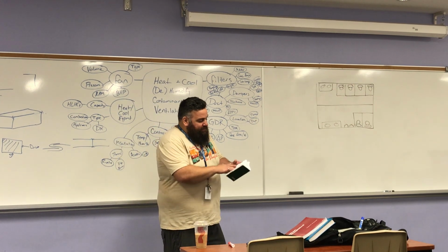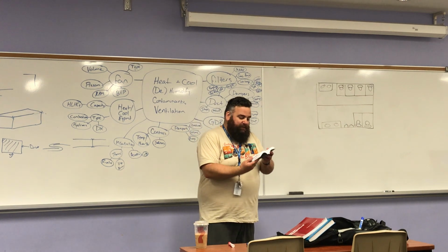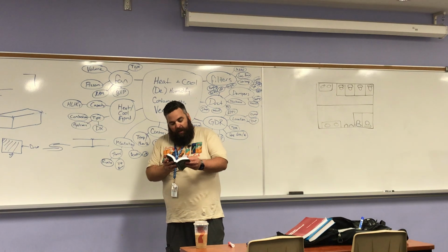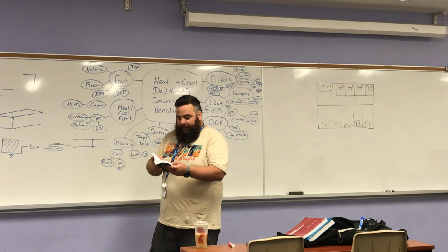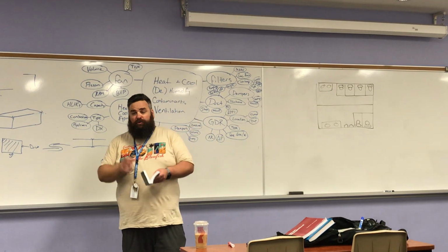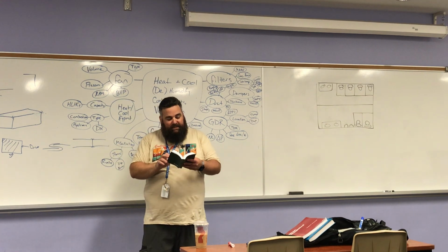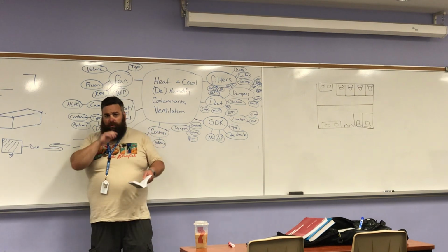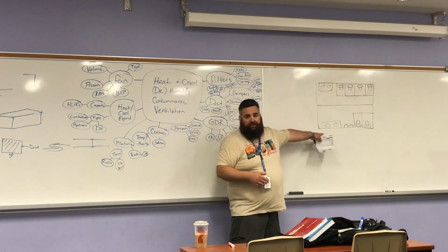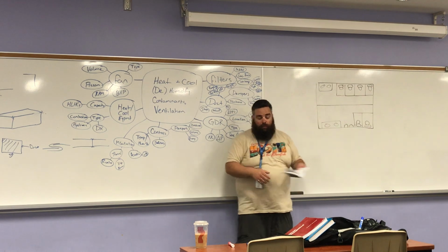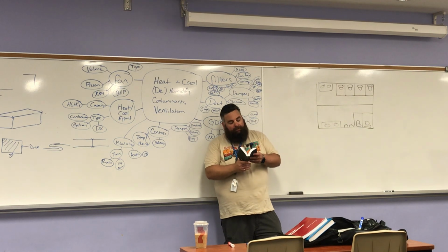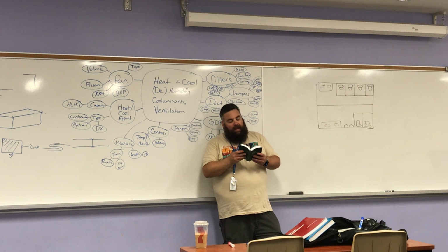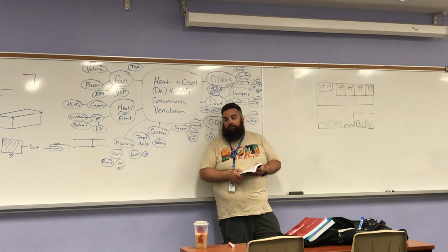So under ASHRAE 62.1, I'm concerned here with exhaust rates. And this is a public toilet, and I have two rates, 50 CFM per fixture, and when we say fixture, we're not including the lavs, the sinks, we're only concerned with either the urinals or the water closets. So 50 CFM / 70 CFM, and we'll talk about that in a second, and this is class 2 air.